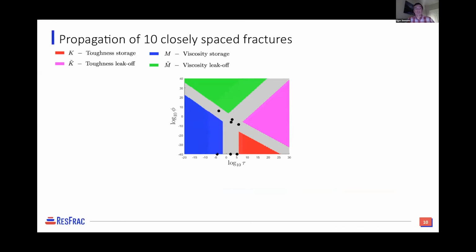And so the geology, in terms of Young's modulus, Poisson ratio, and toughness, is in these parameters. So if you go from hard to soft rock, then these numbers change, right? And also likewise, if you want to try to do a lab experiment which simulates the field data, right? You need to make sure, because you change injection rate, you change injection time, you probably change the rock type. So you move quite a bit within parametric space. So you need to be careful when you are scaling down from field to the lab.